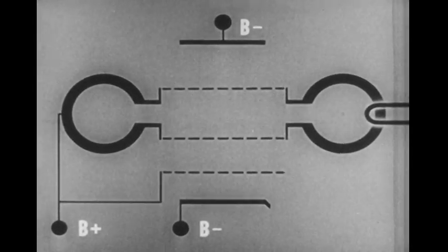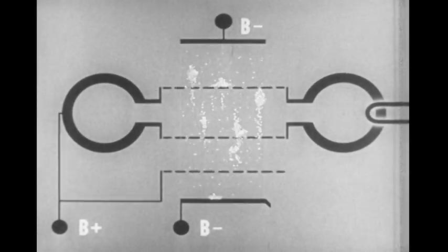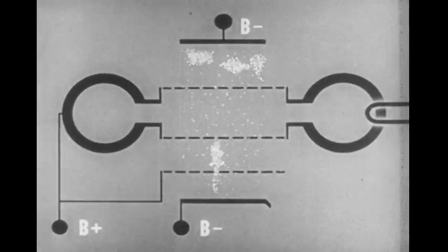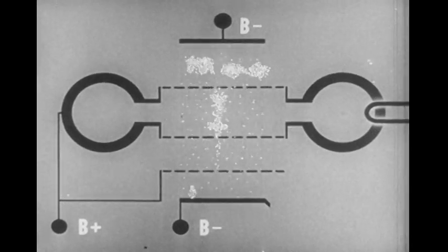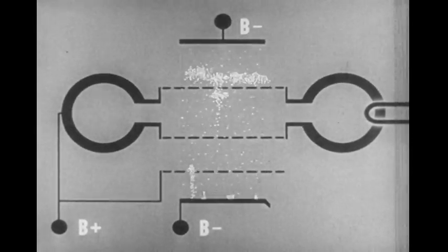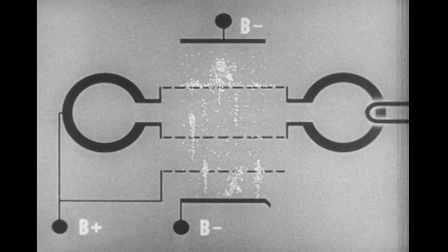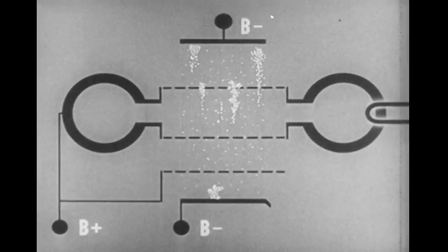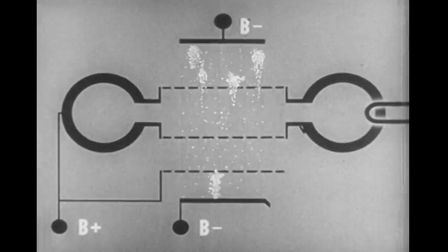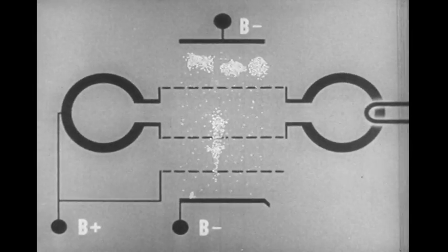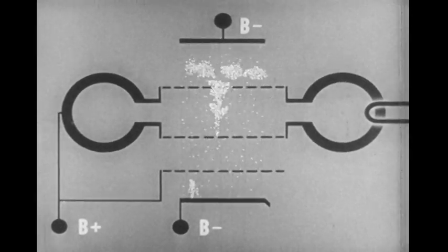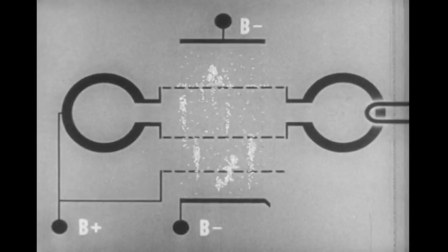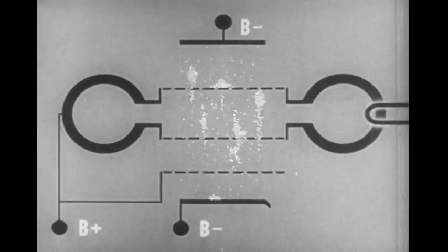Of course, in actual operation, large numbers of electrons leave the cathode and move toward the repeller plate as an electron beam. As they pass through the buncher grids and approach the repeller, they become bunched. And the repeller is so spaced, and the voltage applied to it is such that the bunches return to the buncher grids in the proper phase to give up energy to the RF field. Spent electrons return to the B+ source, either through the grids of the resonator or through the accelerator grid. It is by bunching, then, that kinetic energy supplied by the accelerating voltage is subtracted from the electrons and used to sustain the oscillations in the cavity.